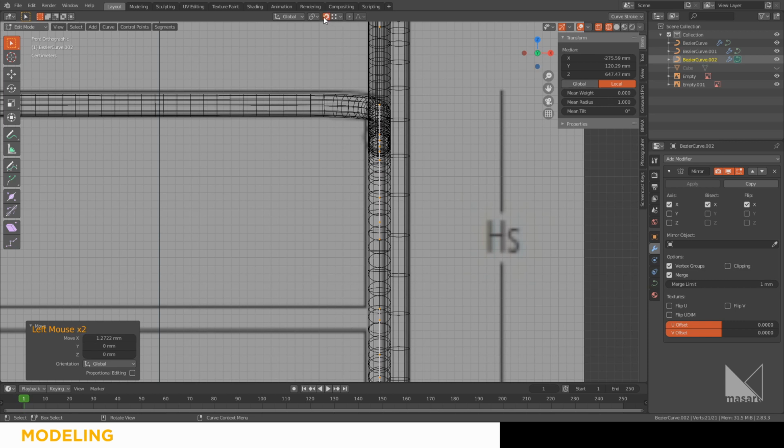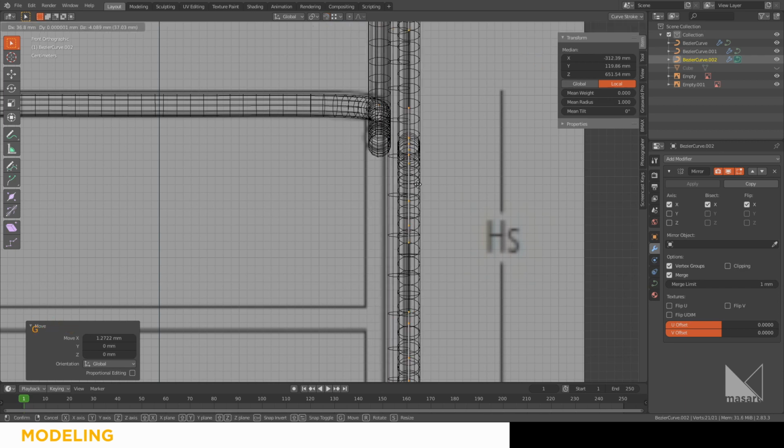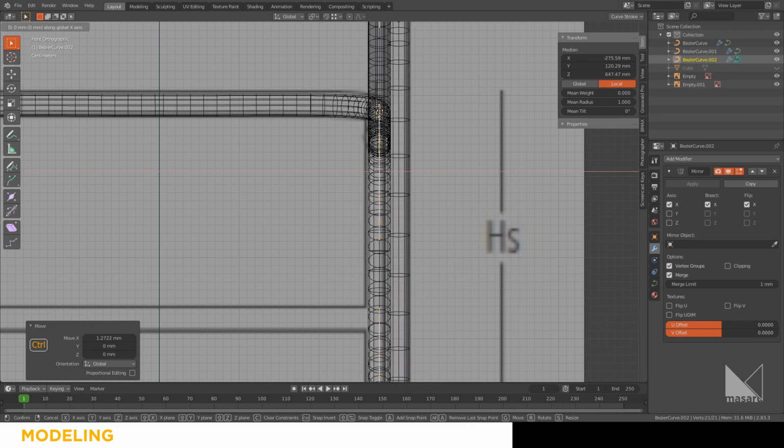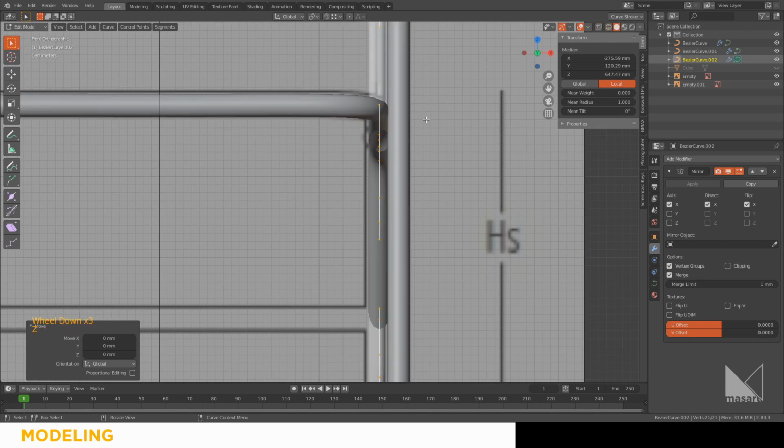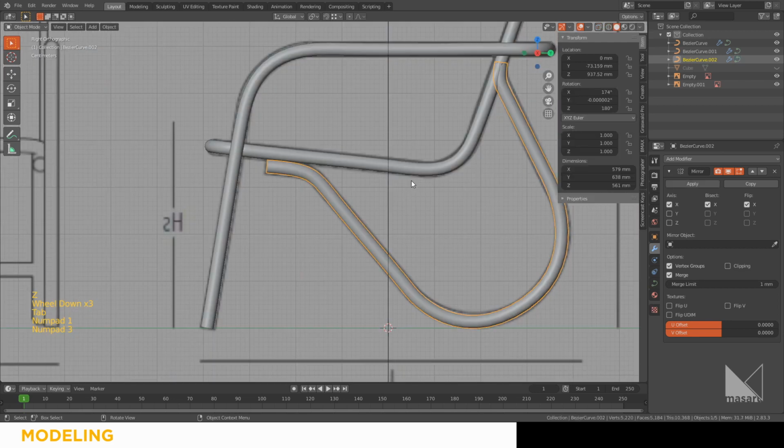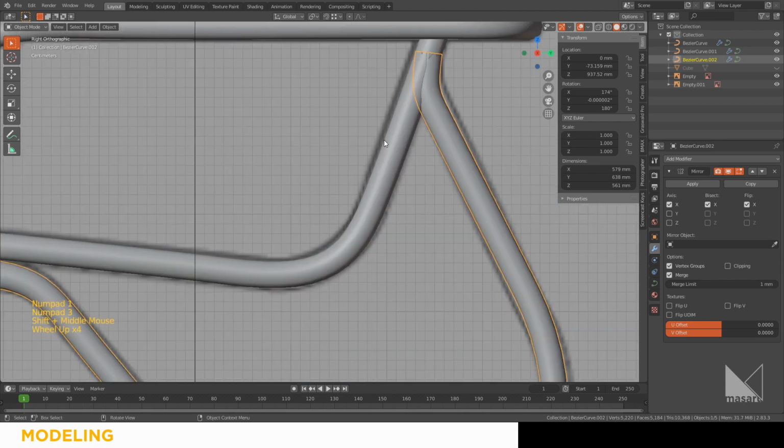When you turn on this one, you don't have to hold the control. When you hold in the control, you will unsnap it instead of snap it. But when you turn off this one, you will be unsnap by default, and then hold control to snap it. So I will snap it to the previous curve, like this one, and check again.